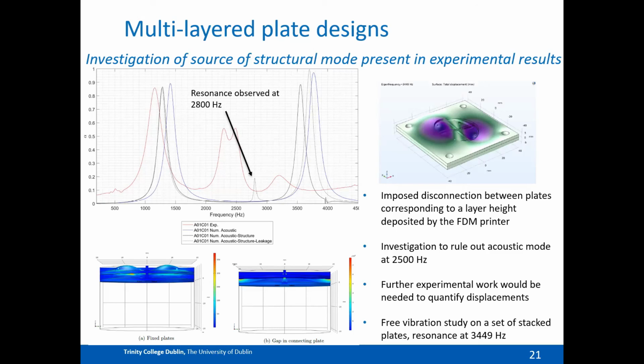But it still exhibited high absorptive peaks at low frequencies, and there could be a change of manufacturing strategy to remove those existing structural resonances, or even exploiting this vibroacoustic coupling, because you get an added dissipative effect. But all in all, this simple design of just decoupling resonators increases your broadband absorption. So you have them acting in parallel, and it's quite a simplistic task.